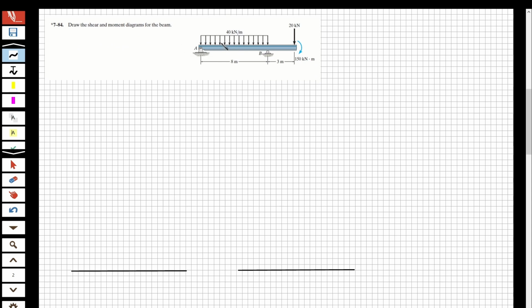In the second question, now you can see we have two supports, and we have here a distributed load, and we have a moment here, and we have here AY, because this is pin, and AX, and we have a BY. And so now let's solve the question. I'm going to draw the free body diagram of the question here.